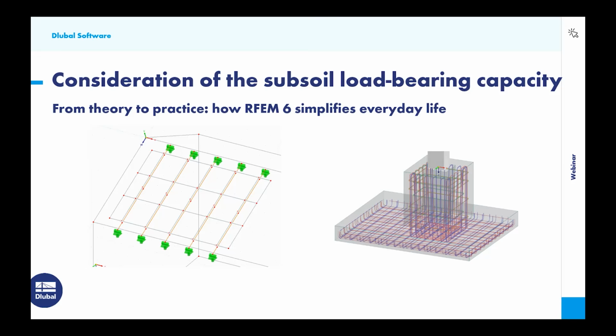Our RFEM program is a free modeling environment. You have a free space. You can model everything from members, shells, solids together in one environment and find an equilibrium with all effects that are needed. And in this case, to simplify it, to explain it, I show you the photovoltaic system not supported on single supports on the roof tiles, then combined with the rafters of the roof to consider both stiffnesses in the deflection. And on the right side you also see a picture of our program, the final output.